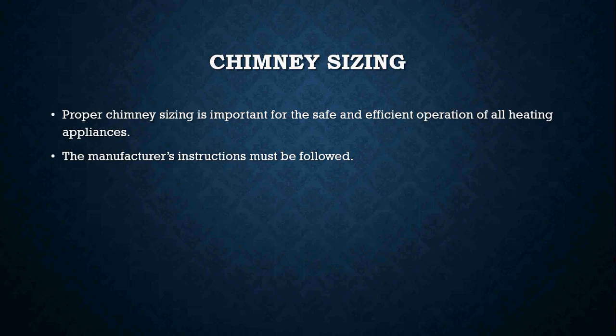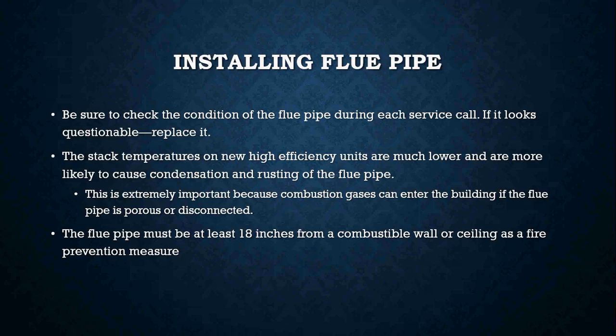When it comes to chimney sizing, it is important to make sure that the chimney is sized correctly for safe and efficient operation of all the heating appliances that are connected to it. However, you have to make sure that you follow the manufacturer's instructions when installing these furnaces, to make sure that they're compatible. Installing a flue pipe, be sure to check the condition of the flue pipe during each service call. If it looks questionable, simply replace it.